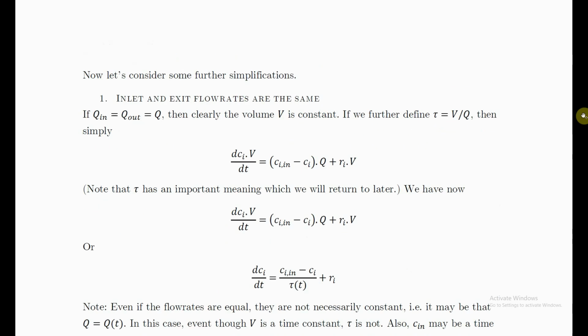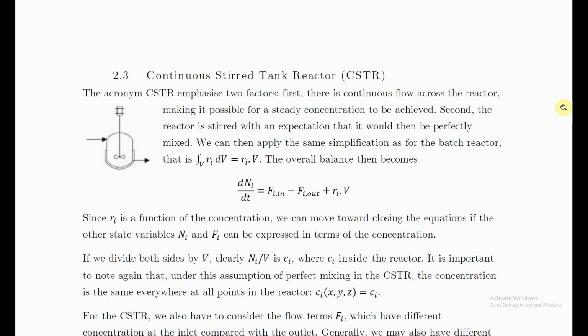And in a similar way, in our CSTR, it's very hard to get perfect mixing the way we mean perfect mixing here. Yes, you can stick a stirrer in and agitate as much as you want, but you won't get infinitely fast mixing, which means that every molecule can instantaneously and always see every other molecule. So that would take an infinite amount of energy in the real world. Nevertheless, we go ahead and make that assumption and we use it. And it turns out to be a fairly good assumption in specific cases.